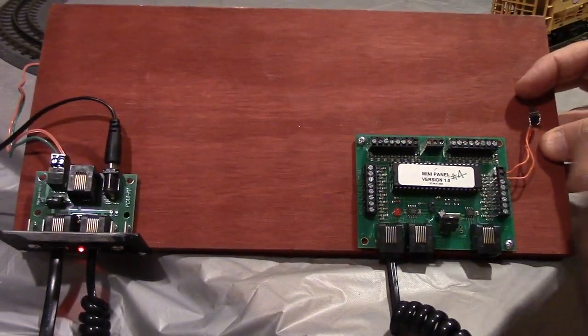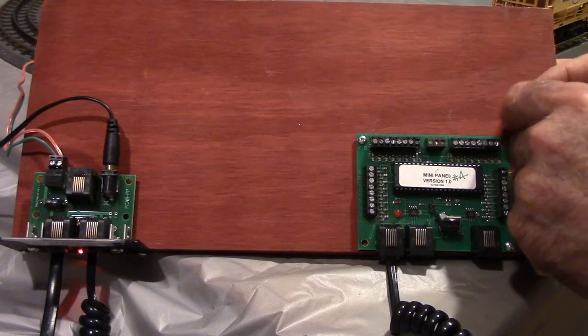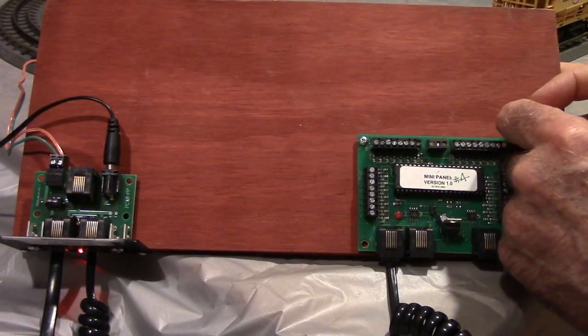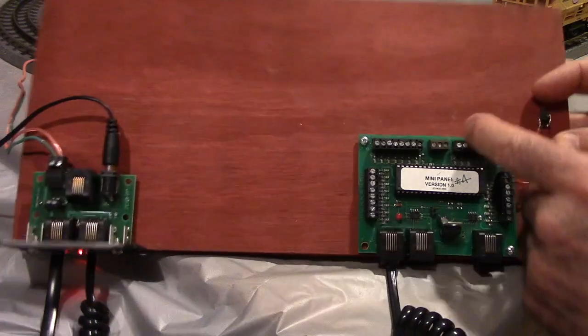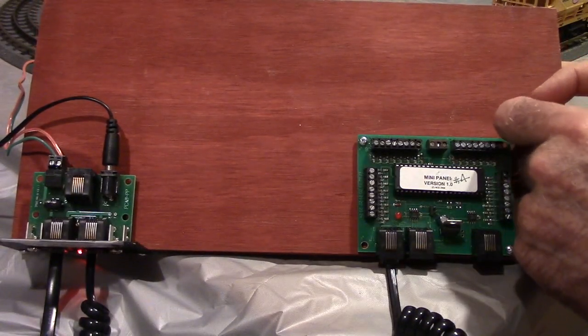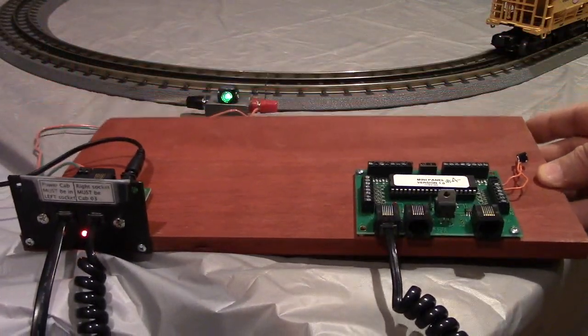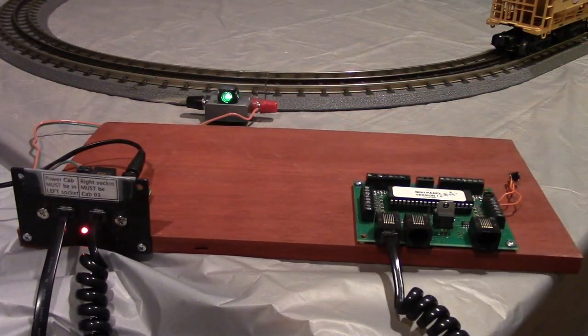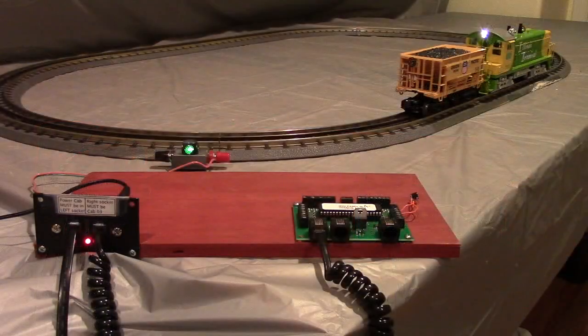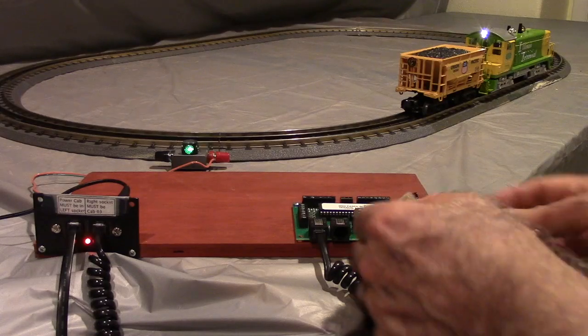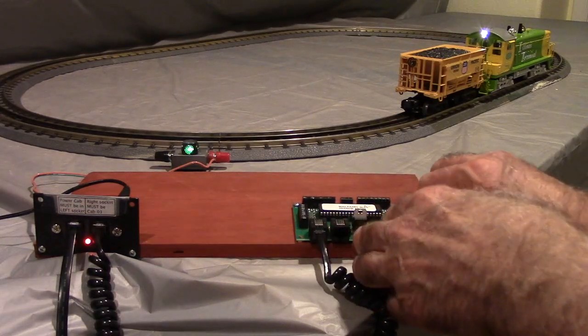And this button on the side is a reset button. If I push this, it blinks the LED, which you can probably see right about here. There's a red LED. When I push this reset button, that blinks. That also blinks when it sends a command. But now we've got our controller hooked up and ready to go, and we'll put a small program in it. To program it, what we'll do is plug a cab into the programming port, which is over here.